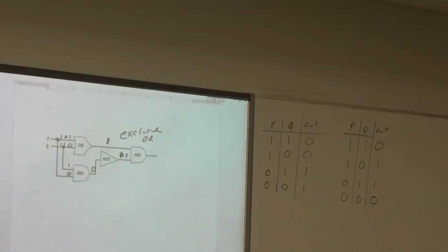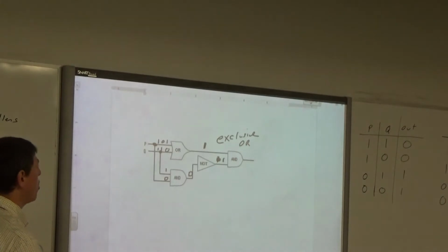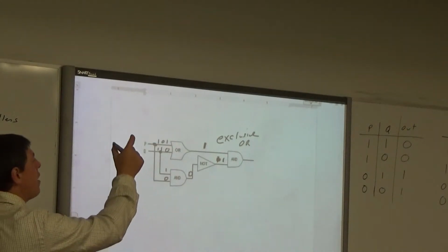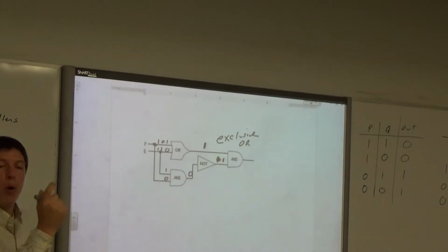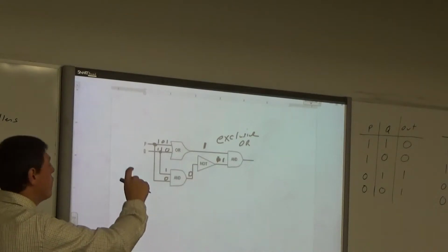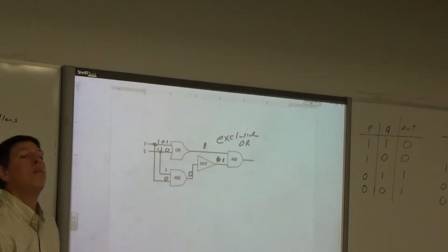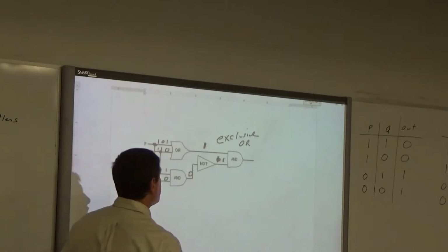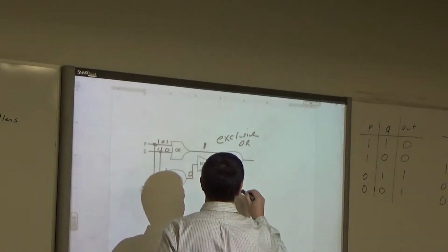Okay? An exclusive OR means that the only way that you get an output is if you have one of them false, one of them true, okay? This circuit is actually used quite often when you're building breadboards or building other things in the computer, okay? Because you don't want both, you want basically to say, if they're the same input, whether the impulses are on or off, I want that to be false. The only time I want it to be true is if one of them is true, okay? Usually in computer science, I see this as the exclusive OR.